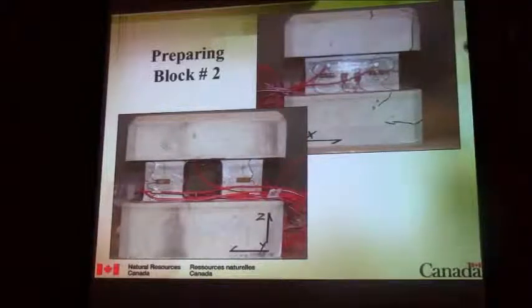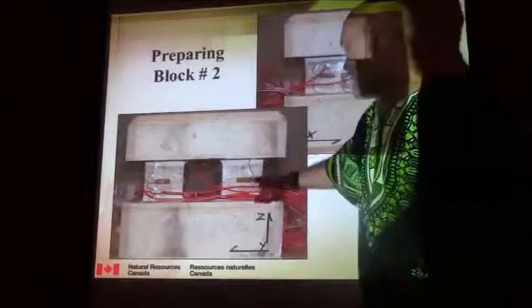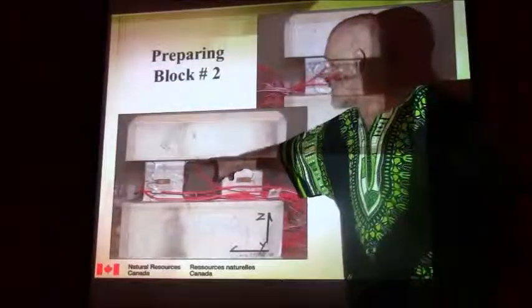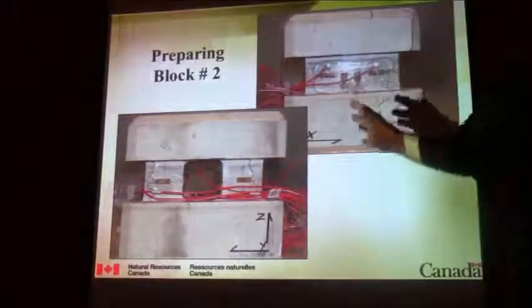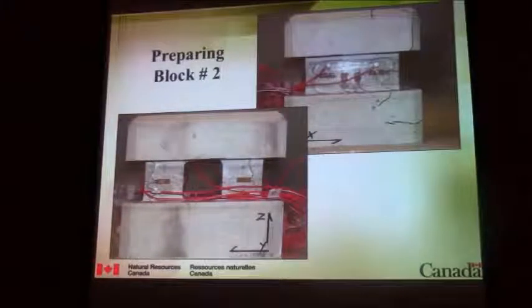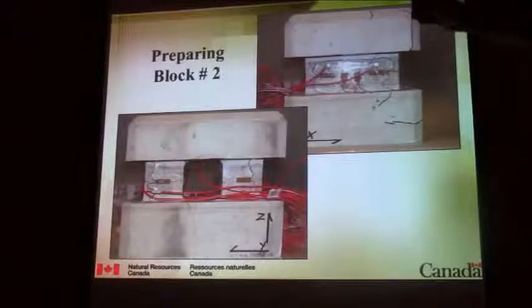So the idea was, as we were going to load this, we had various strain gauges and little acoustic emission sensors. You'll see later on we even had a camera inside here. We put all sorts of instruments in here to see how the rock was behaving as it started to fail. And then the idea was that as we started perhaps to see a concentration of acoustic emissions, we'd see the pillars being damaged. That would allow us to recalculate when we would think it would fail.